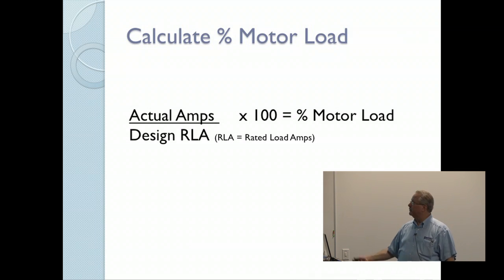You may find you're at 60% load. You can do a quickie calculation there. So if you're at 60% load and you've got a 10-degree delta T on design, maybe you're just doing a 6-degree delta T and everything checks. Okay? So now I'm getting into, don't just write down numbers, what can you do with them?